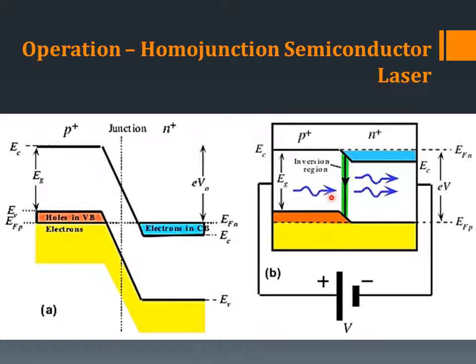These spontaneously emitted photons in turn act as stimulants and stimulate further recombinations of electrons and holes to occur in the active region, leading to the emission of more coherent photons. Hence, the emitted photons have the same phase and frequency as that of the original inducing photons and will be amplified still further to get an intense beam of laser.